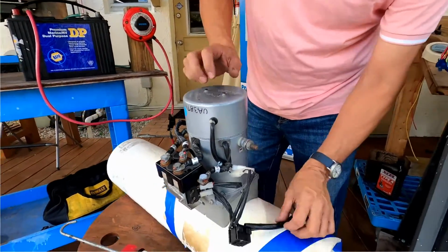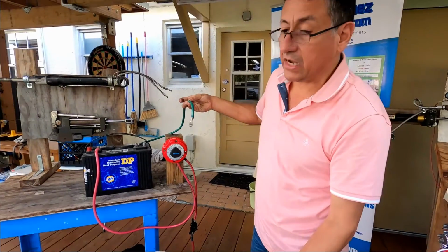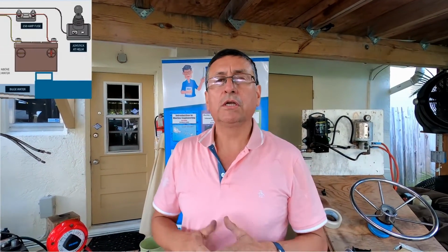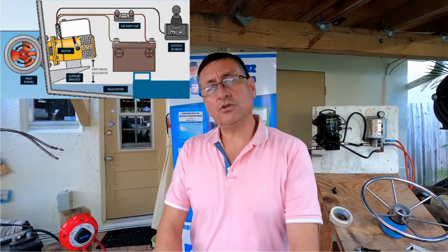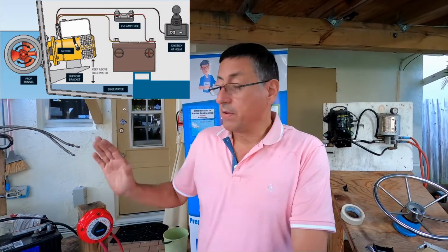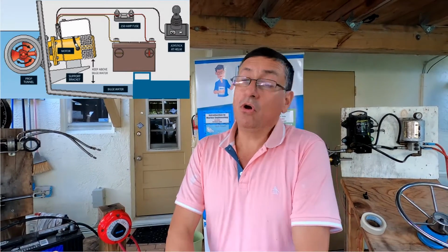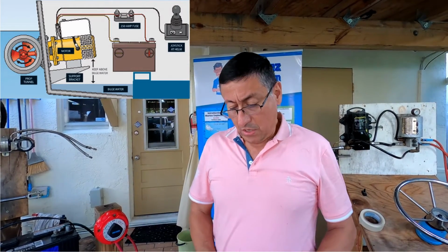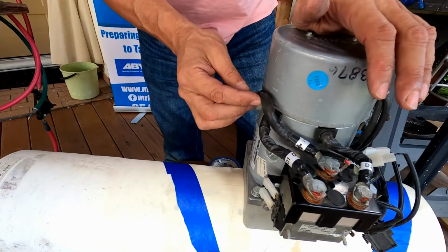The connection is simple. This is the negative bus bar. The negative bus bar should be connected to the negative of the battery bank. Those bow thrusters come in 12 volts or 24 volts, depending on the boat, depending on the length of the boat. If the source of power is 24 volts, it is because the bank of batteries is connected in series. Batteries of 12 volts connected in series. Or if you prefer, you can buy batteries of 24 volts directly. That's your decision. Okay, the positive goes into the positive terminal of the motor, and the positive enters